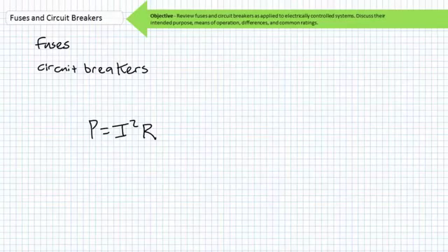They stop current flow. Current protection devices are placed in series with the electrical load they are intended to protect, because elements in series with one another carry the same current. This is the most basic of series properties, and protection devices make use of this fact to selectively enable or disable current flow. If a protection device is closed, it allows current flow to the load, whereas an open protection device does not.